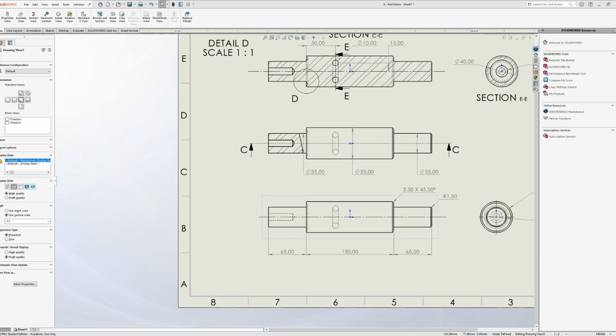The top view, both in name and location, is showing more detail specifically about that screw hole, just based upon the cutout, but it's also allowing us to see that slot on the far right as well. So for something like this, having a cross section isn't even necessary. And that's why I only did that partial cutout on the far left. So I guess what I'm getting at here is don't mistake the cutout on the left to be a full cross section.